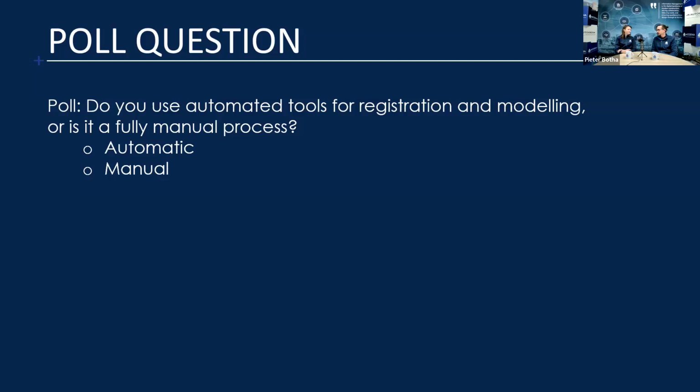So we have a top view based registration, which basically places the scans in their correct position of where I've scanned them on site. And then the cloud to cloud at the end would be to refine that registration, just to bring that accuracy down to where it needs to be, and then provide a very clear, smooth, all-to-all accuracy registration. There are other ways as well for automatic registration within Scene, but those are the steps to follow.